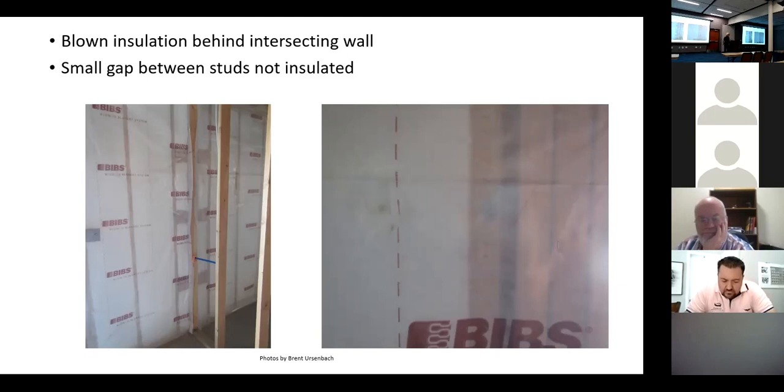And we at the county allowed them for a little bit on our ceilings, those rafters, those ventless places. But then across, not just Utah, but Colorado and other places, we're still finding the condensation issues up there, and that's because they never get installed correctly.